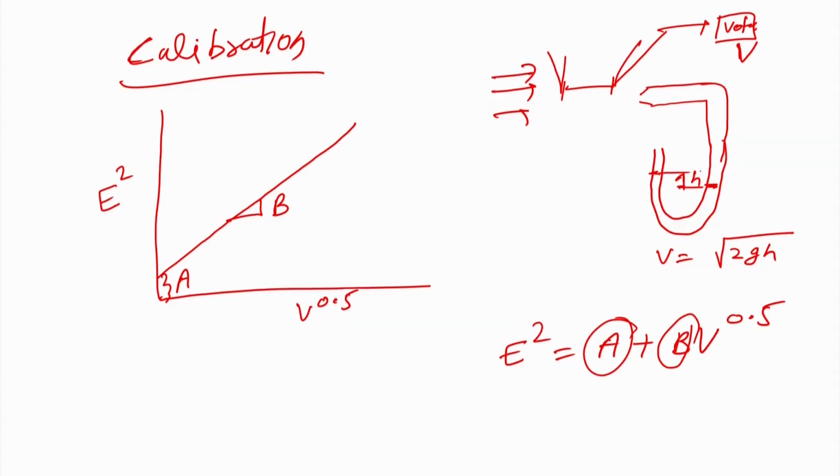You will see that you can acquire the data at a very high speed, and if the flow is turbulent, if the fluctuation level is very high, you can acquire at a very high frequency, and you can not only get the velocity, but you can also get the fluctuations, how the fluctuation is taking place. So, with each fluctuation, the temperature will try to be modified. You will keep the temperature the same, current will be modified, a volt will be modified, and you will see the volt fluctuation reading with time, or E versus T you can get.